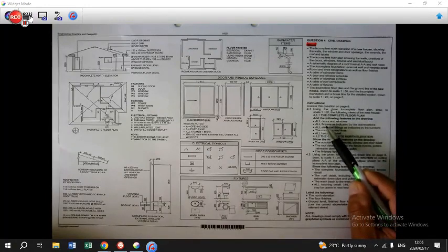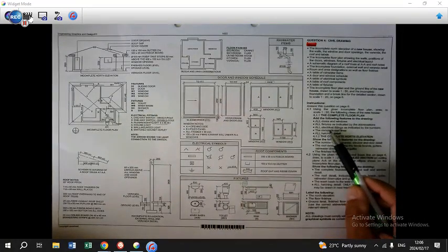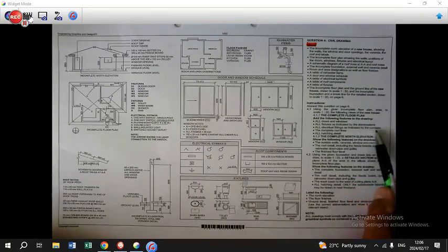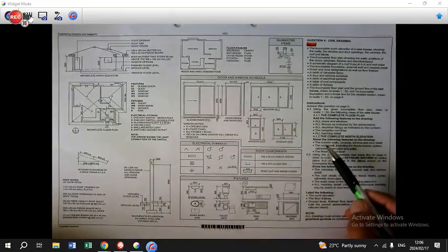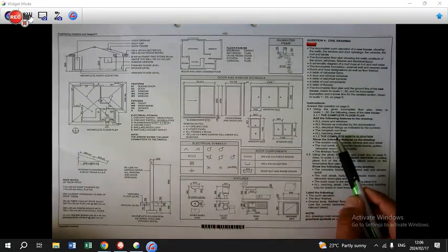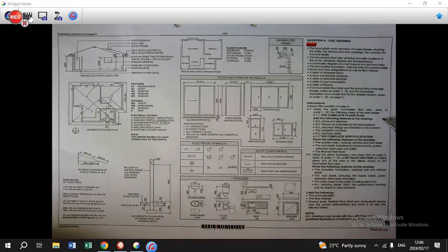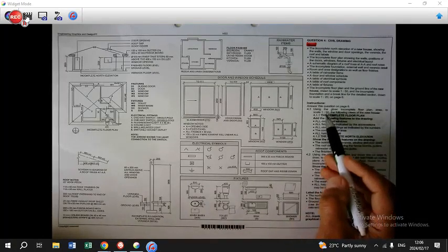All doors and windows, all fixtures as indicated by the abbreviations here, all electrical fittings as indicated by the numbers, the complete roof lines, which you will see here, which have been omitted on the actual page 6, and then of course all the hatching detail required for common brick, and those should be lines going at 45 degrees. Learners, let us apply all of these instructions into our drawing by using a scale of 1:50.